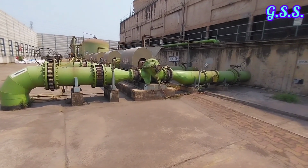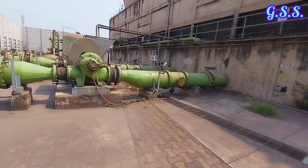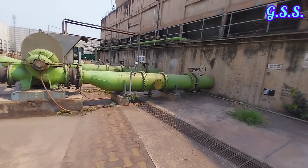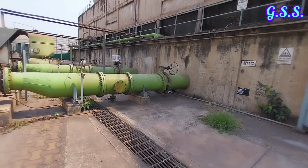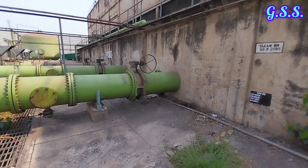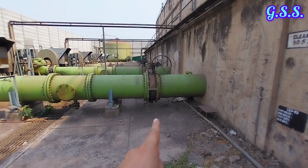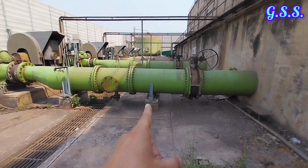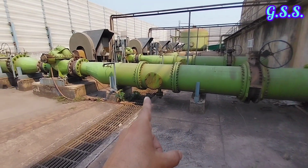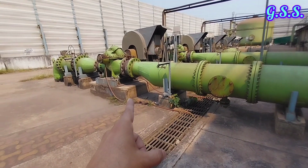This is an installation of cooling water pumps in front of a cooling tower. From the cooling tower side, this is the isolation butterfly valve. Then this is the pipe spool for the conical strainer. Then cooling water comes to the pump suction.